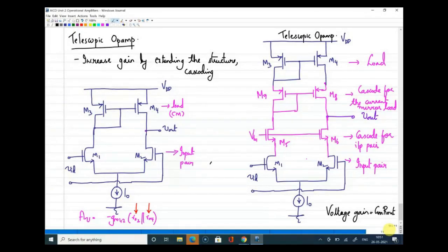All right, so you do not know what the improvement will be here? The output impedance will increase by gm ro. Output impedance, sir. How is it improved by gm ro? So tell me, in the first circuit it is ro1, ro2, right? Now how will it be improved? In which transistors will gm ro get improved?